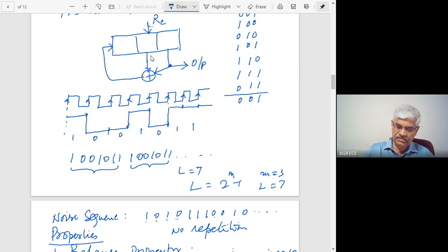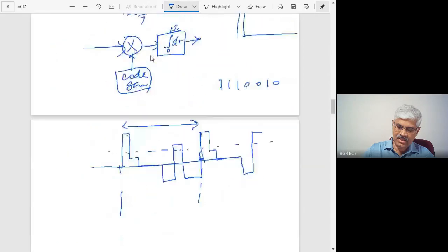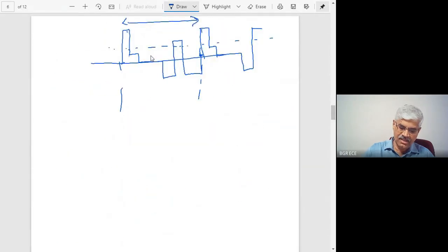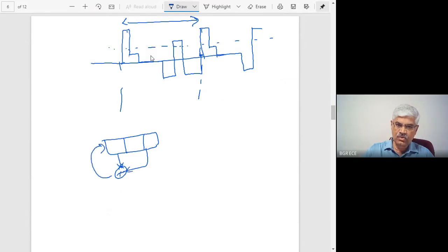Another sequence is, say, suppose I have a shift register, this is one other sequence. This and this, if you give feedback like this. Previously, we had these 2 outputs. Now, this and this. If you look at the output here, again I start with 0, 0, 1. It is not necessary that the output has to be always 0, 0, 1. You start with any other state, it will give you the same sequence. Okay, so 0, 0, 1.